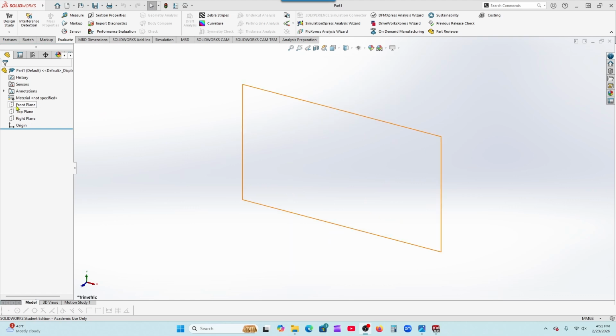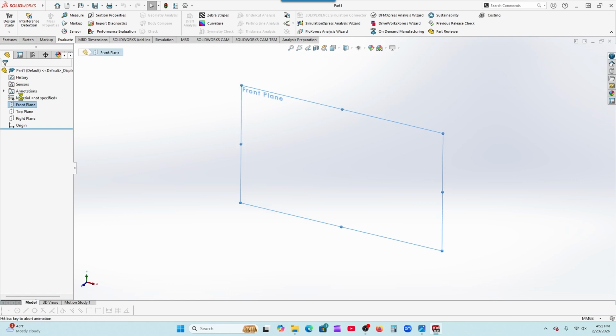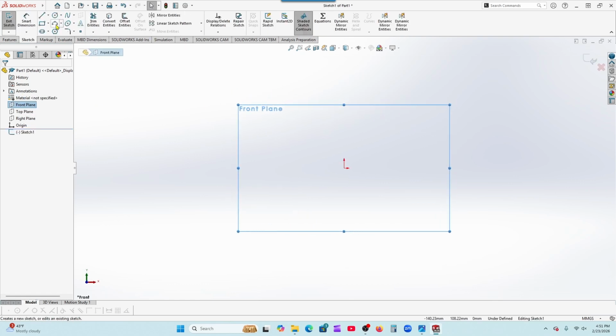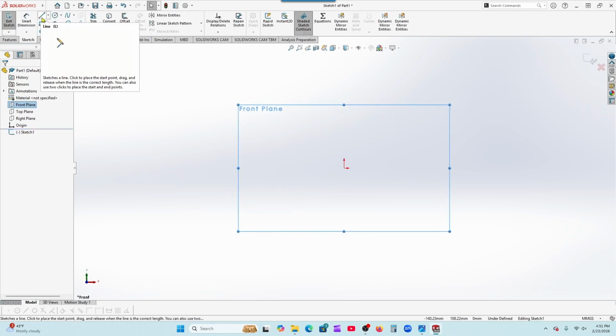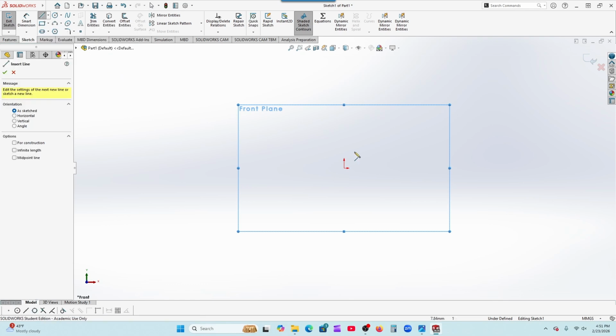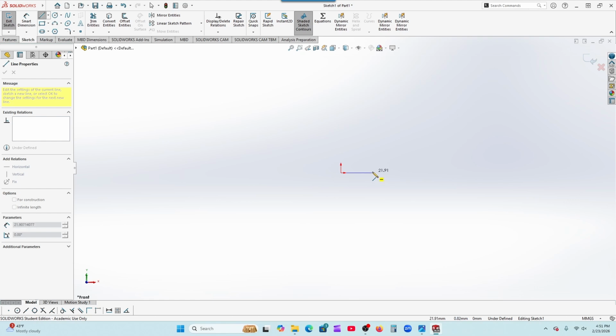When we were drawing our circular parts earlier today, I was telling you that there are two different ways to draw them. You can do a revolved boss base, or you can just do a series of circles, building the part up until you have a finished part. This instance right here, we're going to do a revolve. So what I'm going to wind up doing here is draw a part using that concept.